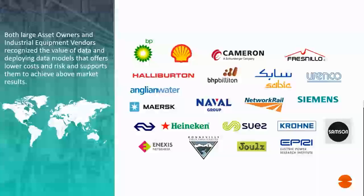Another question is, do I need high frequency data from my assets because I only have second data from my Pi historian? Well, this really depends on the type of failure mode or the type of functional degradation that you want to classify. So let's say you are looking at the degradation of the windings in a transformer. Then the oil analysis samples, if you have a low-end oil analysis sensor in your transformer, so not a DGA one, typically provide data updates every 5 to 10 seconds. And that's sufficient data to see an oncoming trend of particles in your oil.